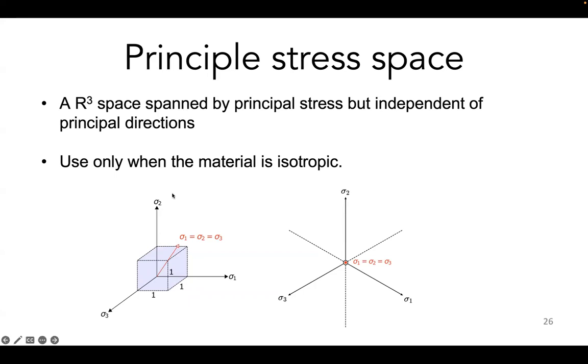In the eigenvalue, principal stress space, what you're assuming is that for a given principal strain, I would always get a principal stress. It doesn't matter where that principal stress happened. The combinations of the principal stress would be identical. The orientations of the principal stress, on the other hand, would pair with the principal direction of the strain. Okay, so that's it.